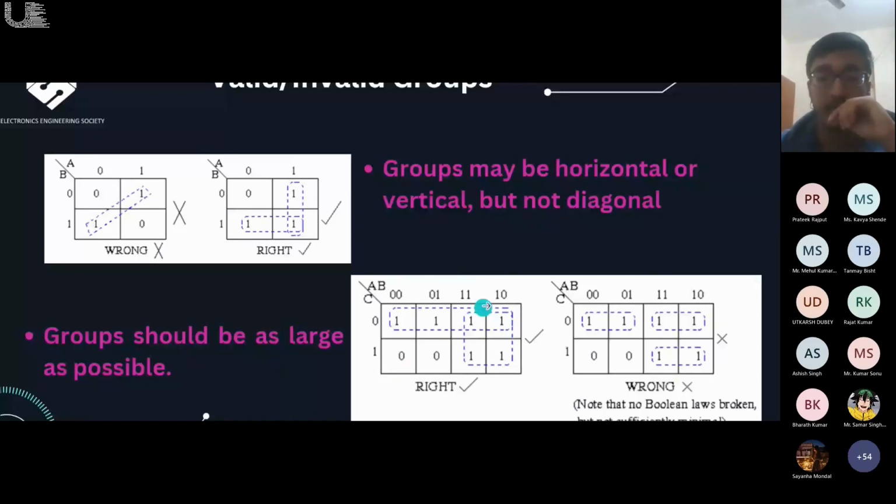If you notice, in every column and in every row, only one term changes. From 0 0 you go to 0 1, and then from 0 1 you go to 1 1. If you went from 0 1 to 1 0, you would have two changes: 0 changes to 1, and 1 changes to 0. Instead, here you have only one bit changing. So this is something called Gray code, and this is used to simplify the circuit. So the boxes represent 0 1 3 2, 4 5 7 6, as I told you. Okay, so these are swapped.